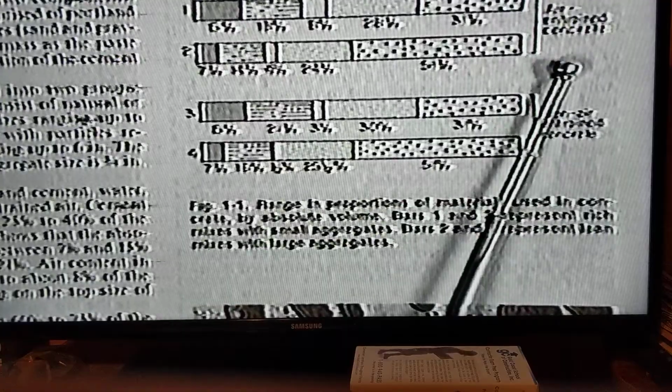Now, what they're showing you here is air-entrained and non-air-entrained. The word entrained just means added. Air-added concrete means that you've got a milkshake that's particularly fluffy. What this does is what you might expect. Air has an insulating quality. It also tends to make something plastic. And so air-entrained concrete has a higher insulation value. It resists freezing and thawing cycles, so it doesn't crack quite as much, and it's a little bit more plastic.